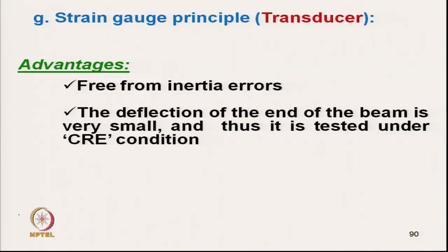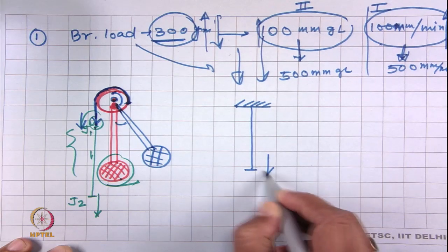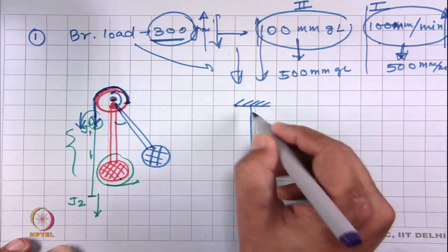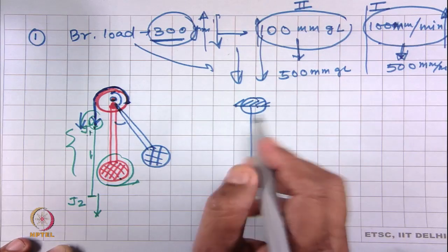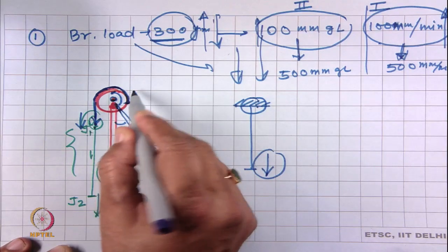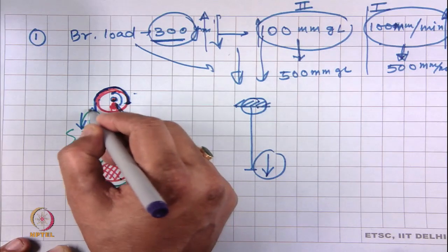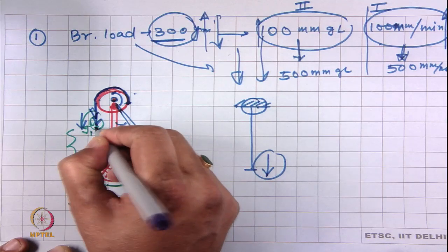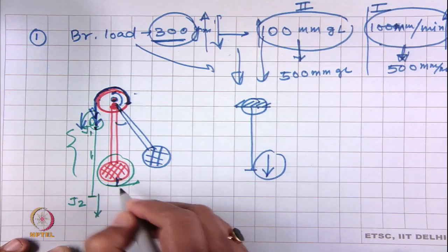because force we have to measure from the other side. Like this is the fixed jaw, this is the movable jaw. The movable jaw moves, we can move it at constant rate, but the load has to be measured in the other direction. In the earlier case of the pendulum, we get the load by direct movement of this upper jaw. If it does not move, then the load actuating measurement system will not work.